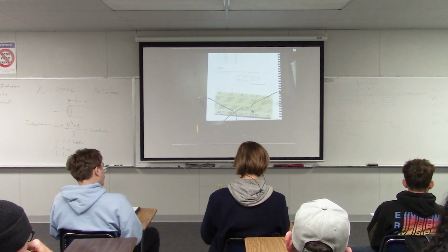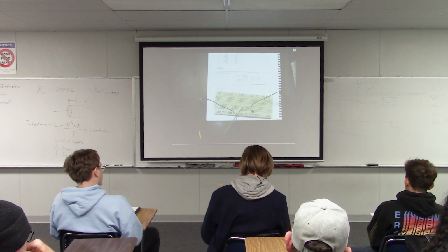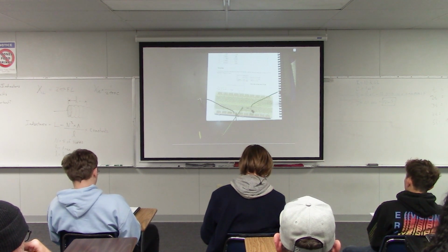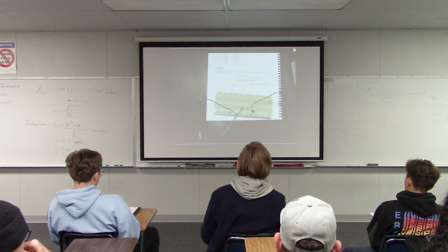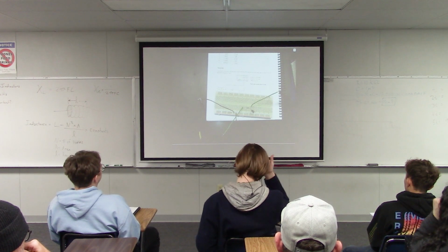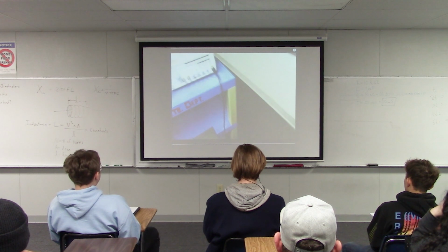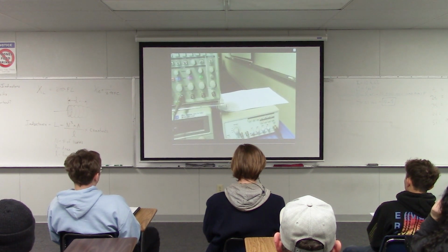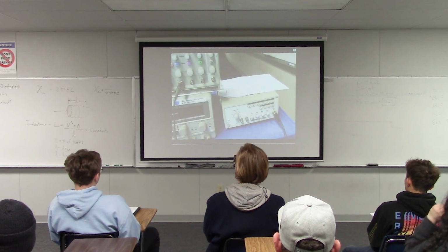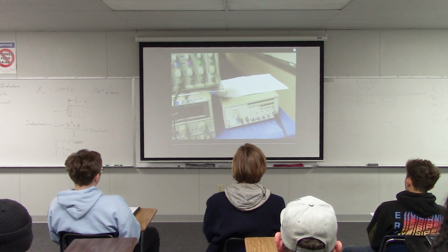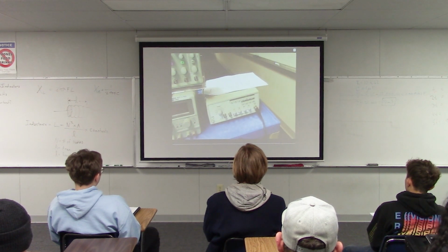Okay. So now I've made all the connections. Now I want to hook up my oscilloscope and my function generator so that I can actually measure these charge times. So what I'm going to do here is turn on my function generator and put it in the square wave mode. And we'll talk about the frequency in just a second.